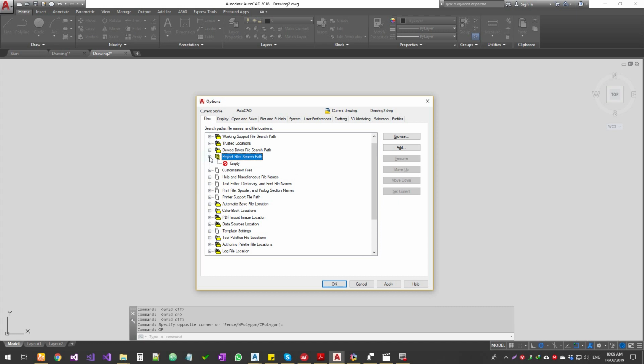And project file and search path, you can set something up here, so that's typical, by default goes into that particular path to find something. And then customized files, so this is your CUI, customized user interface, like how you want the ribbon, what all the tools you wanted, and things like that. So there will be one file that says main customization file, so you can specify it, and whatever you set here is what it predominantly uses.